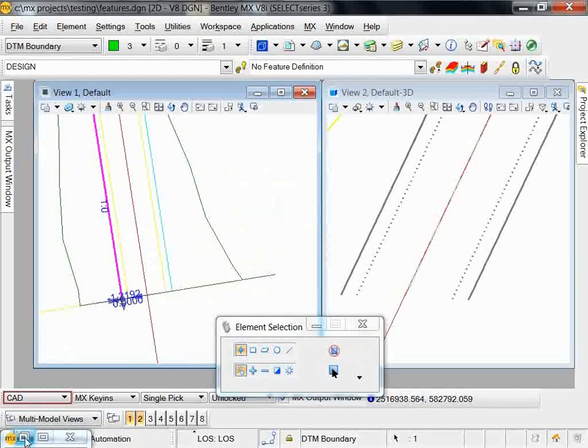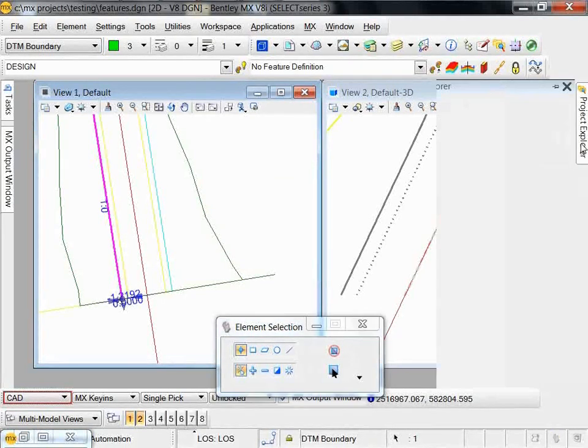So let's have a look at that in the PSS file. In the PSS file, MX has a flat structure, so all of the features are listed just as a flat structure running down through them. That's how they're listed in our typical dialogues. So if we take a look at shoulder's edge, it has one style definition for the plan style set, that is drawing on a level name of shoulders and defining the level properties or assuming them from a DGN library. So how does this work when we link it through for a shoulder's edge and have a look at the properties?